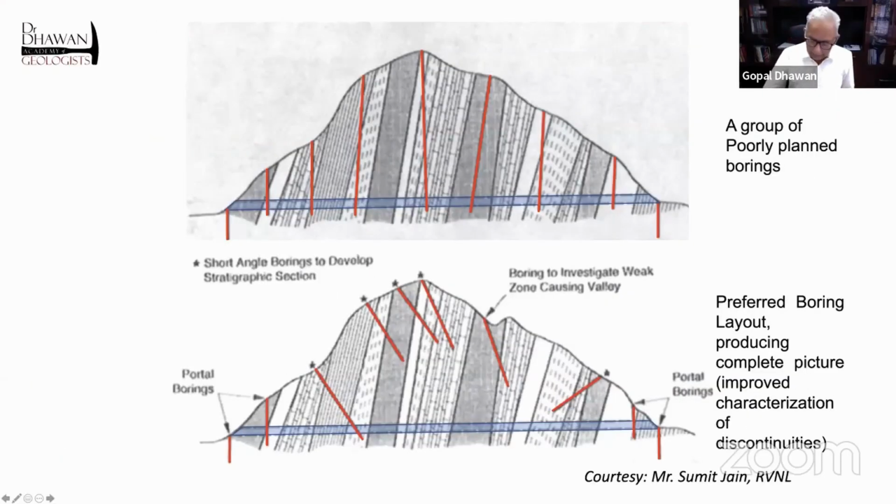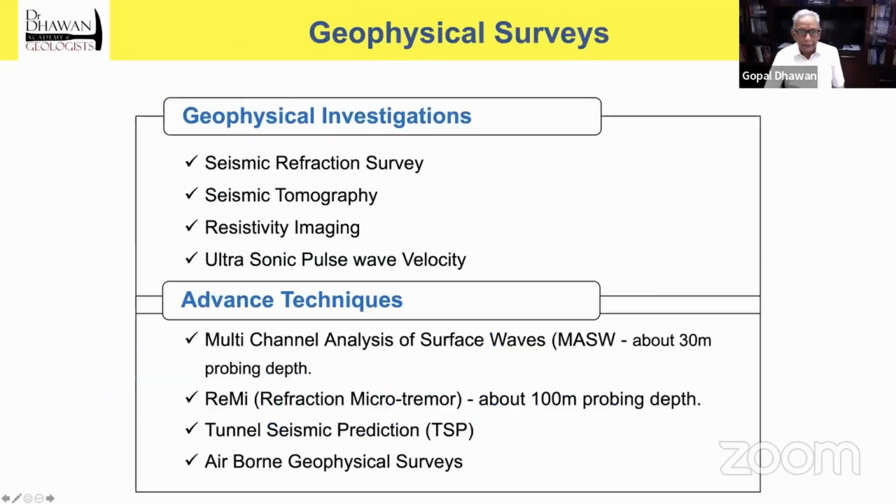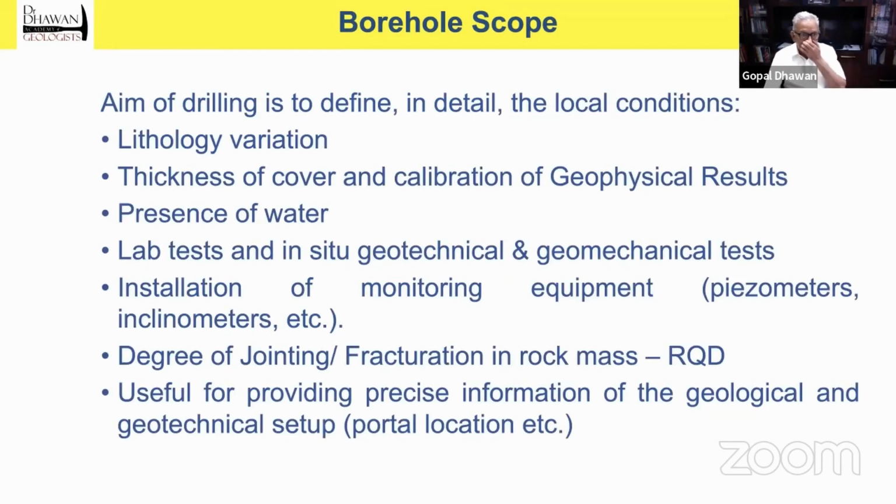And as Dr. Rana said, drilling has to start only after geophysics. I mean, first of all, let us do engineering geological mapping, then update the model. Because the philosophy is that the engineering geological model will tell you something, and leave some gray areas. Now focus on those gray areas with geophysical tools.